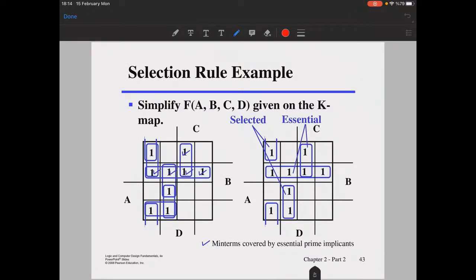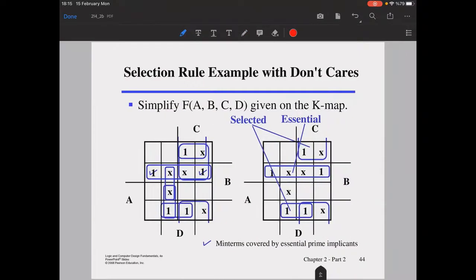Okay, you first define your prime implicant here. This one is essential, as you see, and this one is essential. Why? Because of this. Okay, this one is a key cell, and this one is also another key cell. So I place them right there in their positions, and they're essential. And the other ones are dependent on my selection. I can go for anywhere right here, but just minimizing overlap this time. That's it. That's how we do the selection.